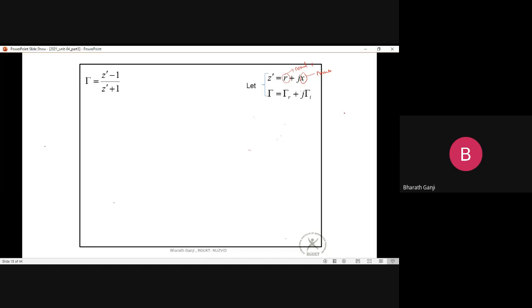For example, on the complex tau plane, someone says, here, this is my point. Of course I know that this point is equal to r equal to 1. Because here this point is the r equal to 0 point, this point is the r equal to infinity point, and the center point is r equal to 1. What does r being 1 mean? That means your z dash is equal to 1, or you can say z is equal to z0. So I can easily calculate for any value.